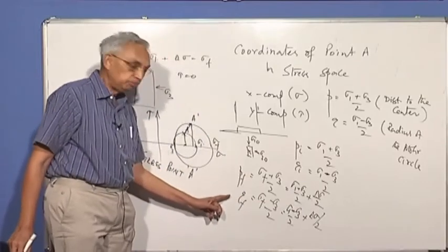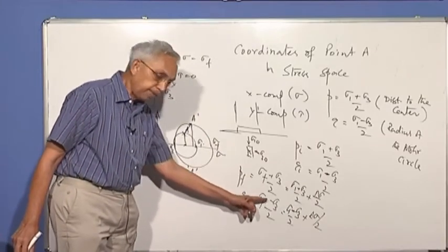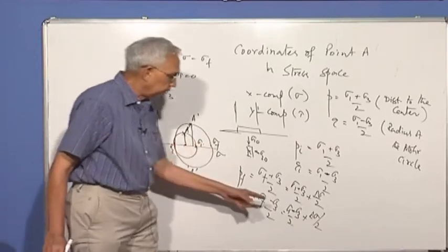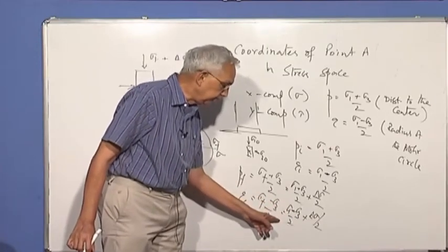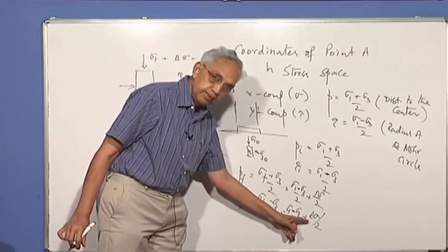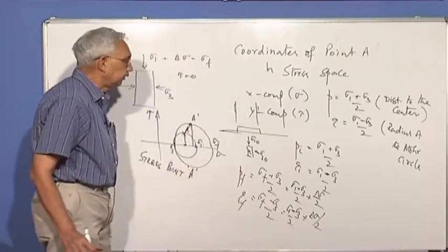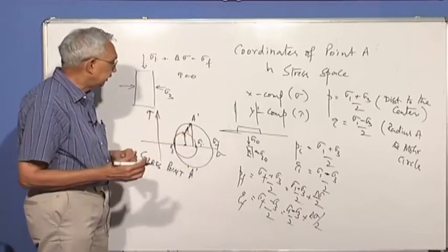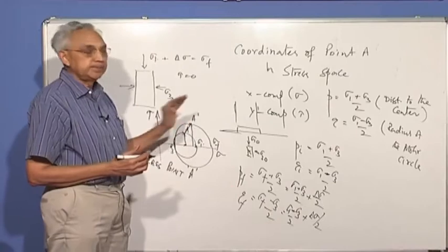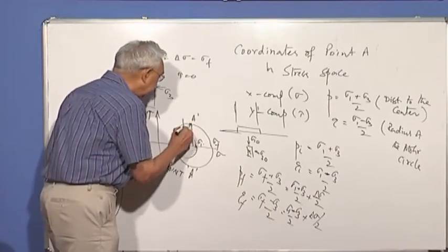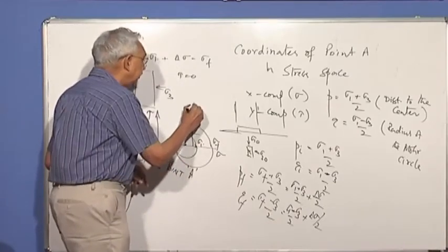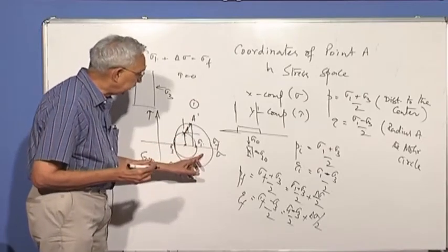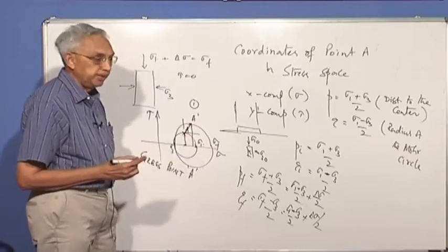Similarly, q_f is equal to (sigma_f minus sigma_3) by 2, which is (sigma_1 minus sigma_3) by 2 plus delta sigma by 2. So it becomes very easy to show the change in stress, in which direction it is going. Can I say that this will be in the first quadrant of the coordinate system? Sigma is increasing, so both p and q are increasing.